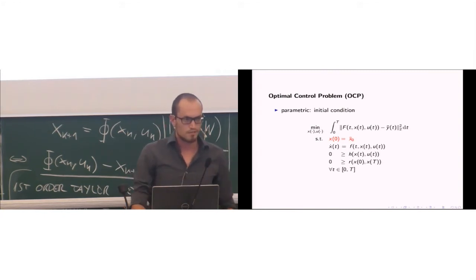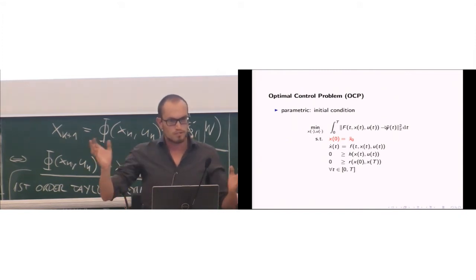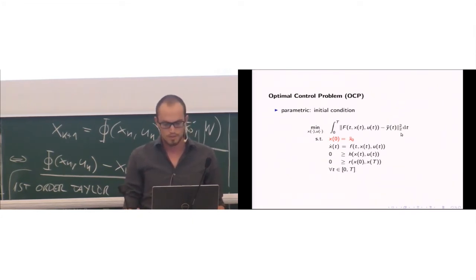Yeah, so I'll go quickly through this, because I think Moritz captured it pretty well, but maybe the formulation is slightly different from how he said it. So this is the optimal control problem we would ideally solve, which is not the most general case, because if you look at it, we already assume in continuous time a nonlinear least squares objective, right? You see this function f popping up, but it's the difference between this f and some reference trajectory. This y bar is something you give, defining the problem, but it's in the squared 2-norm. So it's a least squares form, which is very convenient because we have algorithms like Gauss-Newton that are especially good for these kinds of problems.